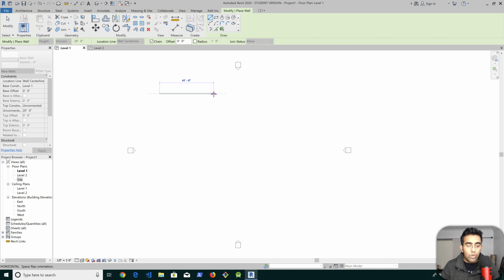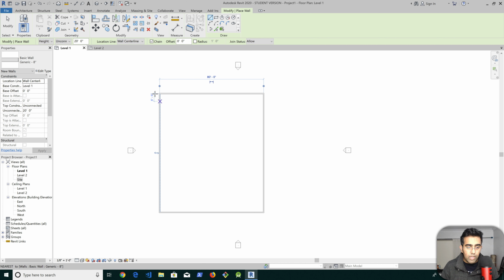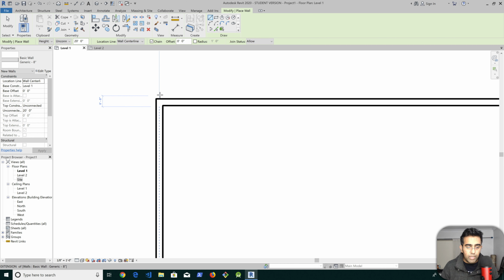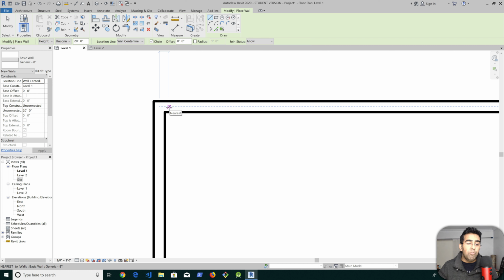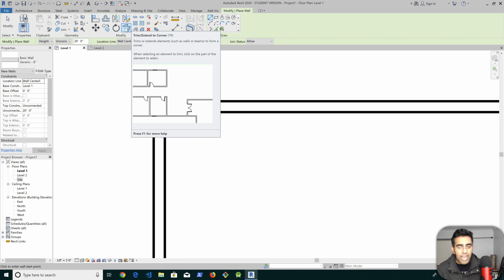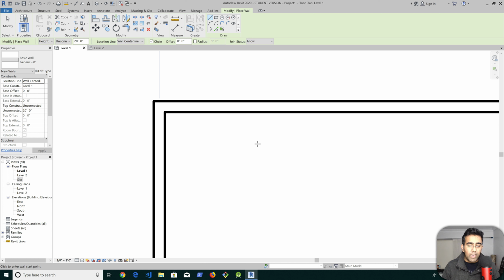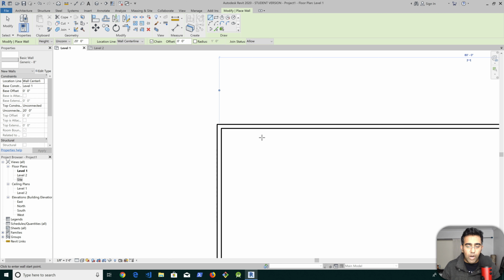in 3D. So we start by clicking, and I'm gonna just roughly create an outer boundary. Click here and then just click here. Now to zoom in, use the mouse wheel to zoom in, and you can see it automatically fillets those lines. This terminology is coming from AutoCAD, and here we have the fillet command as well. I think in Revit it's called trim and extend. In AutoCAD it's called a fillet. Okay, so it combines the corners. All right, so now we have that.